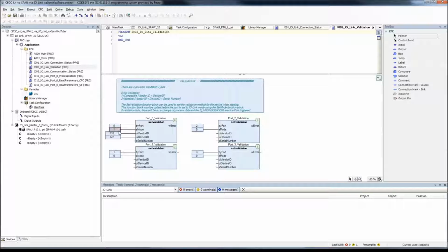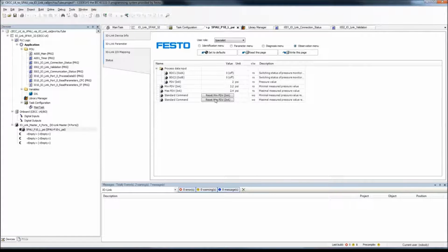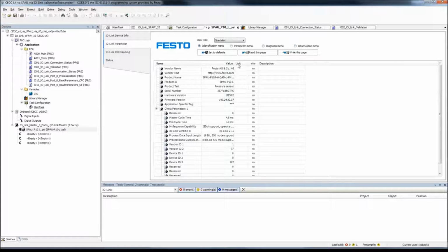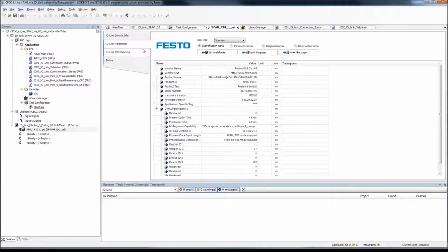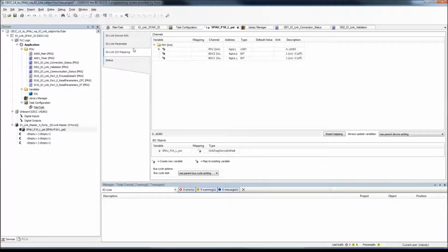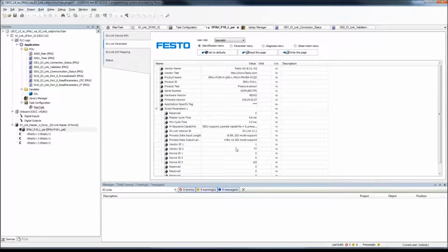And then 1 types in like written here, so you need to have a proper vendor ID and device ID, which you input right here and here. And then the third one adds a serial number, which you would input here. I never use the serial number, I'm just doing the vendor and ID. And if you go to your identification page, you've got vendor ID, device ID, and you've also got the vendor ID here and here, and the device ID.